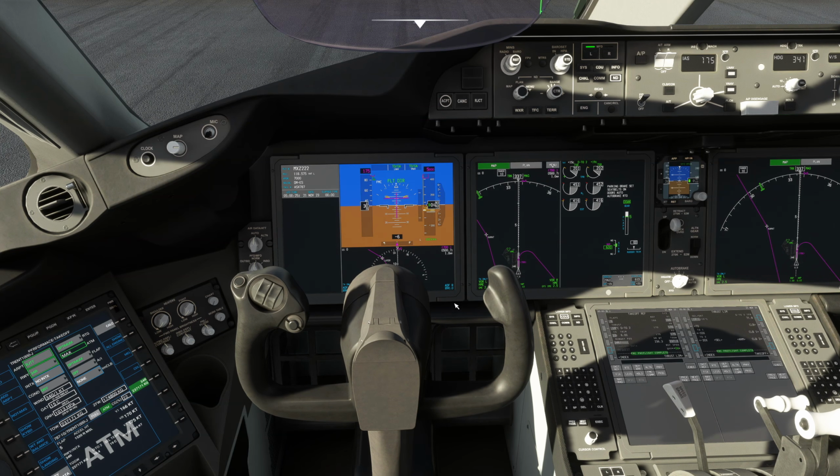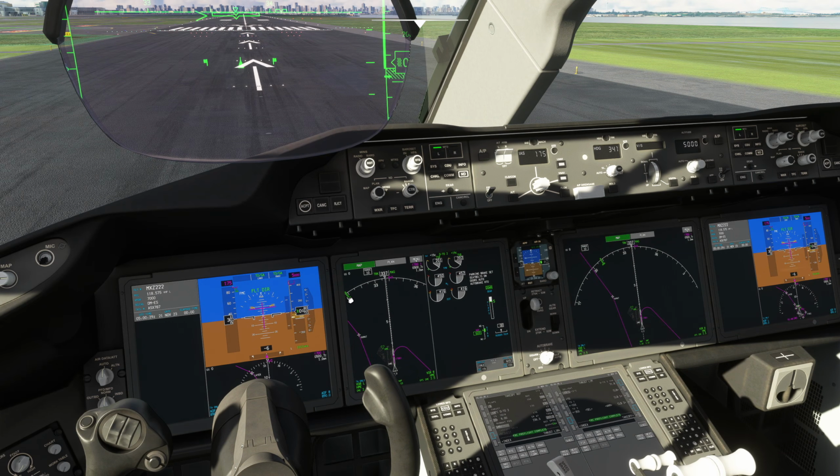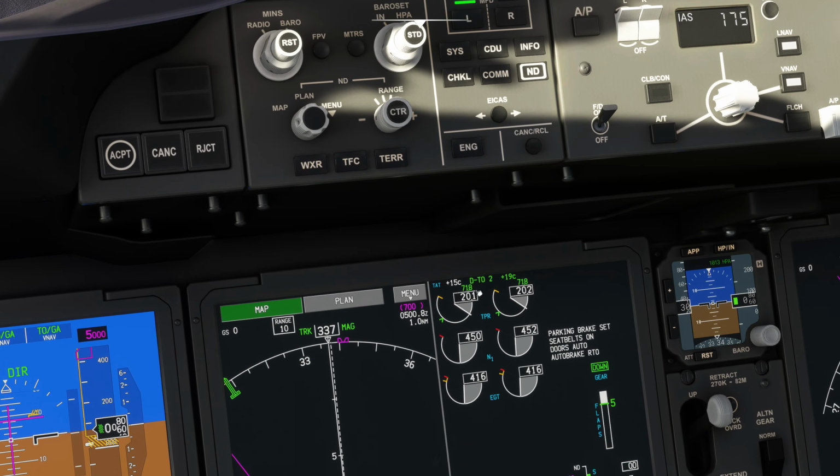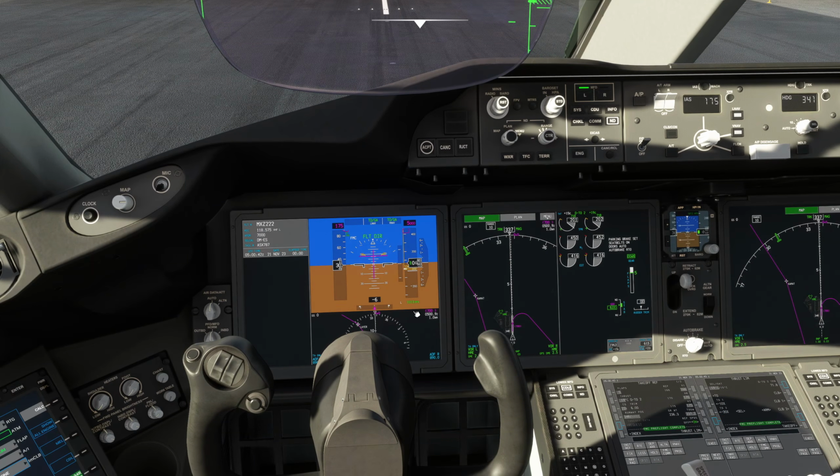Now, you'll then press this button and the airplane will roll and accelerate, and you'll get takeoff thrust. You want to have takeoff thrust set, which today is going to be 71.8 TPR. You can see the number there, which is also shown by this green chevron. That should be set by 80 knots. As you reach 80 knots, you're going to remove that forward pressure on the yoke, and you should have had the call of thrust set already. It's very hard to do that with a single pilot, but that's what we would expect to happen if there were two of us.